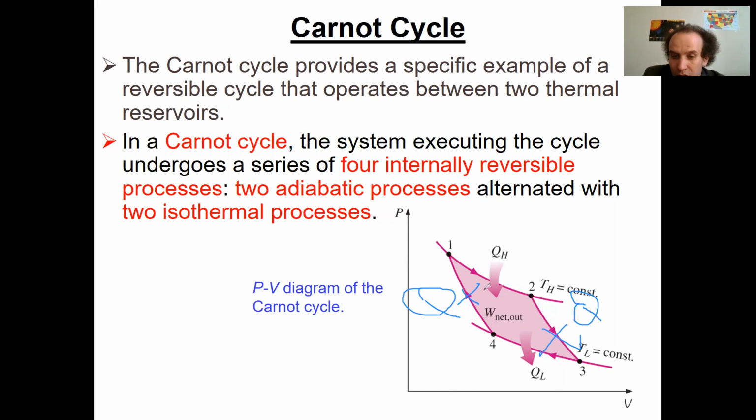And work over the cycle will be what you see crossed here in this picture, right? It's work over the cycle here. So you may realize from here that heat QH goes in, QL goes out, and you may clearly see what this work is. It will be QH minus QL. Do you understand this? So QH minus QL gives you work over the cycle, how they call it, net work, right? Do you agree with me?